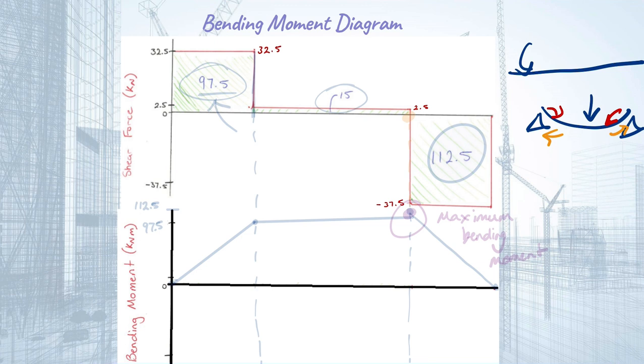So drawing this is a very similar principle on the graph to our shear force. Essentially what we're doing is taking the distance calculated, and we're using the values calculated here as the distances that will go up. But here we're always going to start at 0. So we start at 0 and then we go up to our first distance, and we want to plot that in line with the edge of this box.